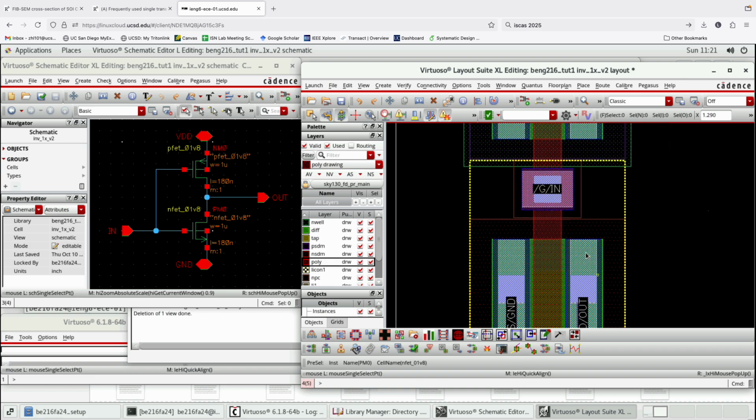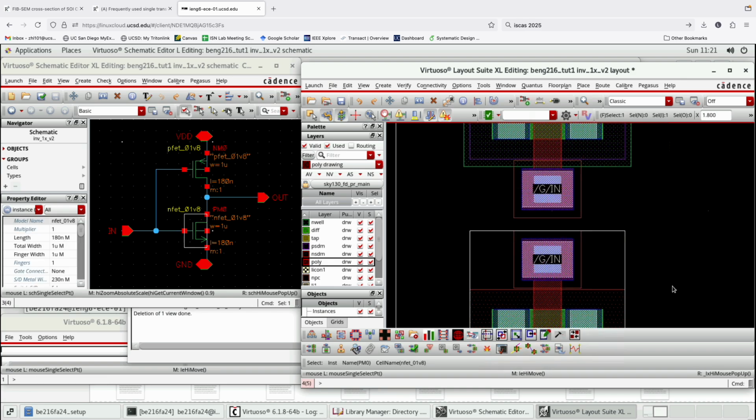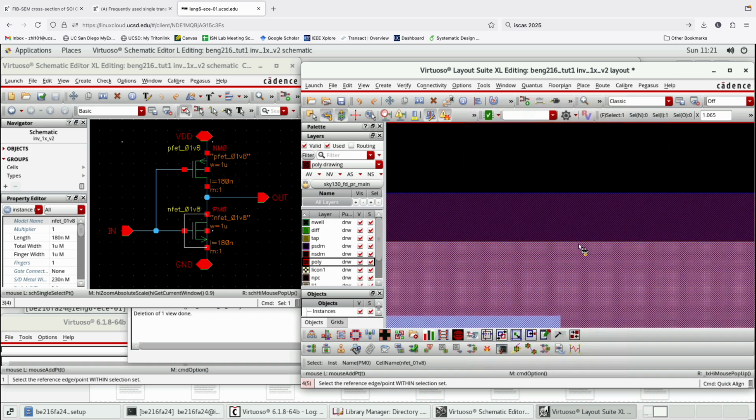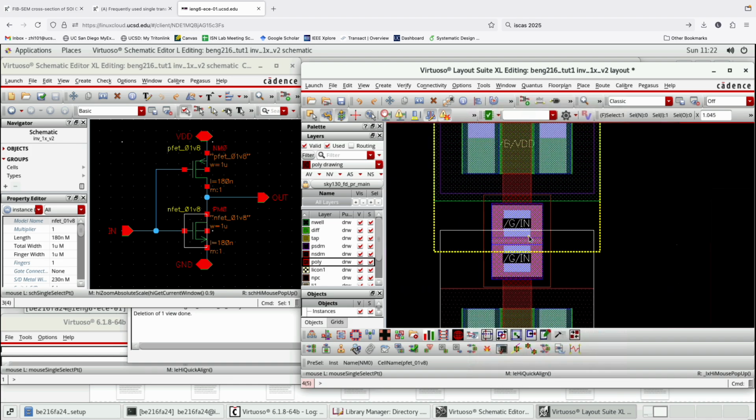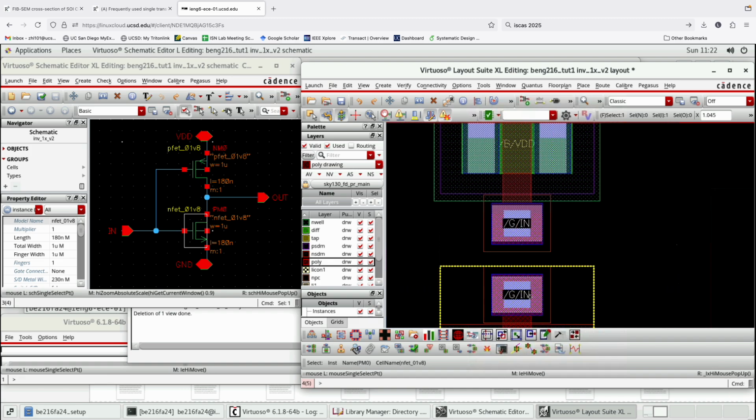So what I did just now, let me try this again. I press A, and then you can either select a node, which will light up like this, or you can select the edge for alignment. If I select this edge, and then select this edge, these two edges are going to be aligned or connected. You should play around with this because it's a little bit hard to explain in a video, but you'll get it very soon. Always remember: press A, then tap on the first thing that you want to move, and tap on the second thing that you want to move the previous thing to.